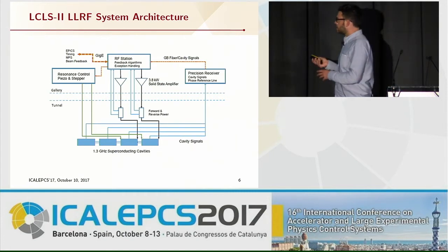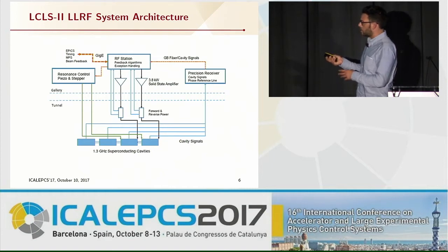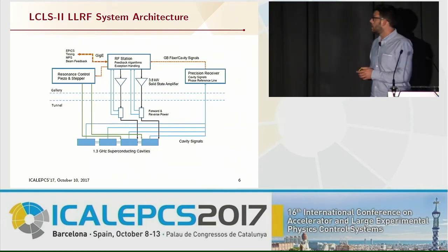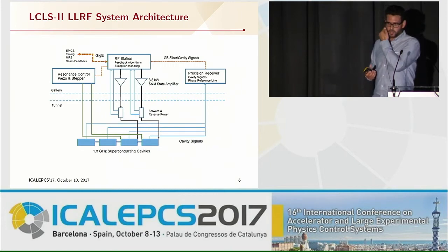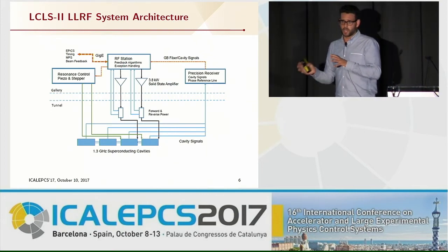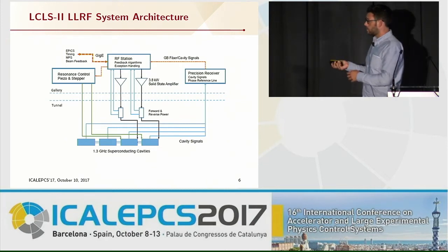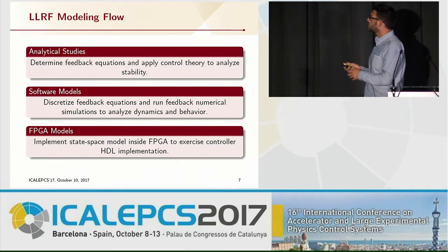So what we did is separate the sensor from the feedback algorithm implementation into separate chassis, and they're interconnected through fibers, so they're opto-isolated. We get better than 90 dB channel-to-channel isolation within one chassis, and better than 120 dB channel-to-channel isolation between two channels on different chassis. So that's the main focus of this design.